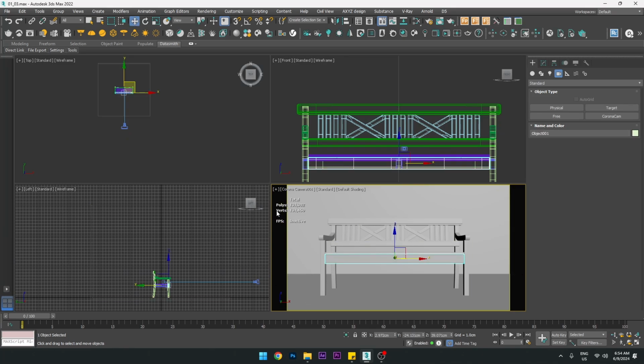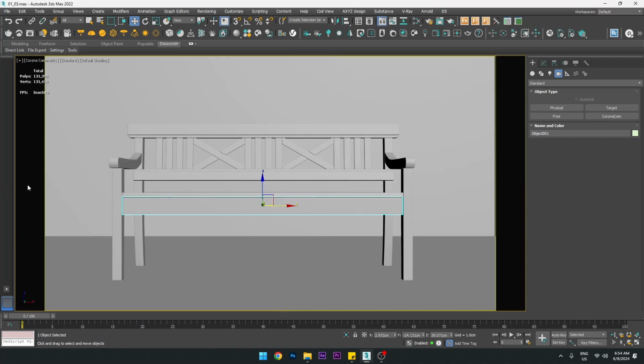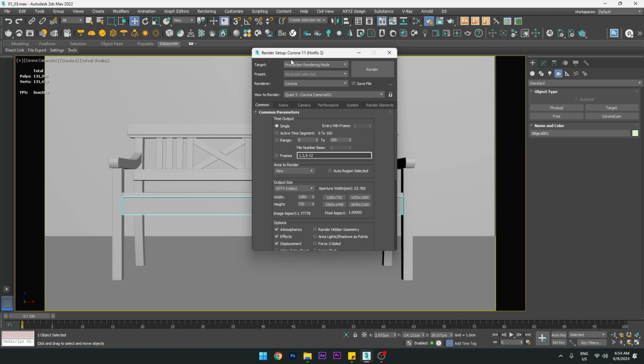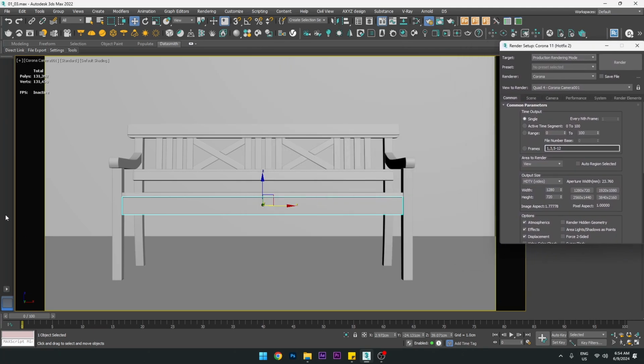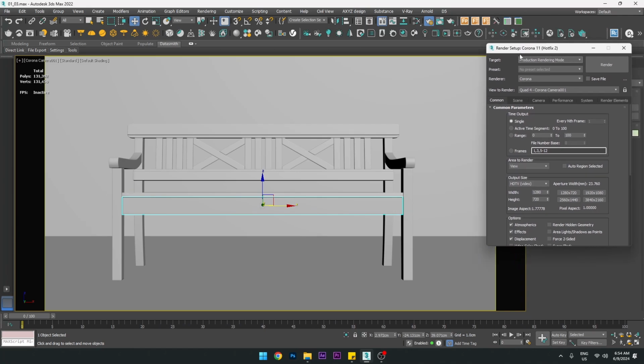So you can see that there are two black bands that are coming up in the viewport, on both sides of the viewport. What it generally means is that these two areas will get clipped when you are doing the render. This is how your render frame will look, and that is based mostly on your output size and the aspect ratio that you are giving here.